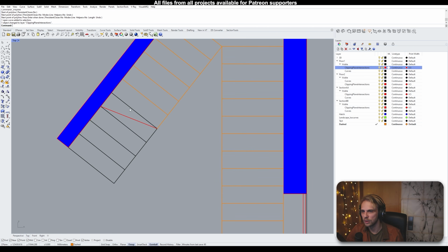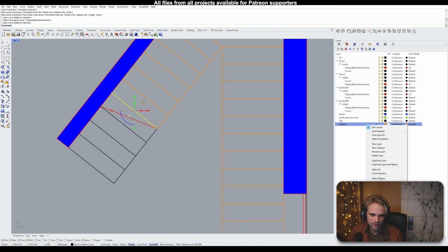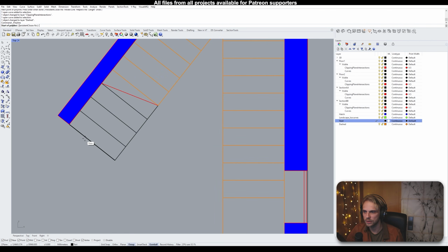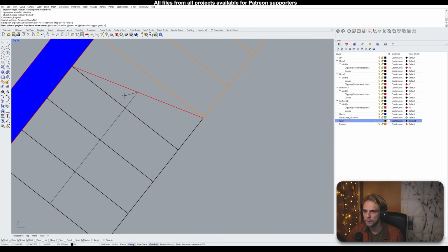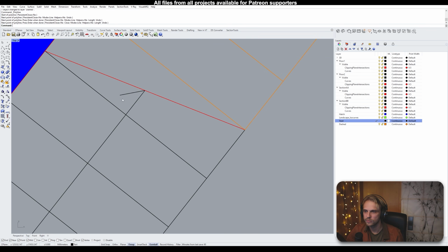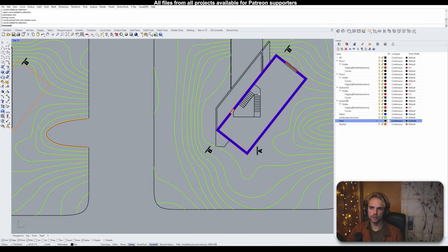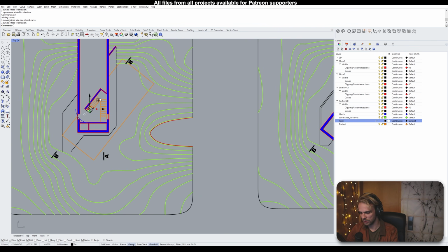This is very AutoCAD-y, isn't it? This becomes dashed, right? And that's it. Now for the text, we just create a small little arrow. Should probably explode this, mirror this, just like that. Trim, and there we go. We have ourselves a little arrow here. That's that. Now in terms of creating arrows here, I will actually just borrow this one.